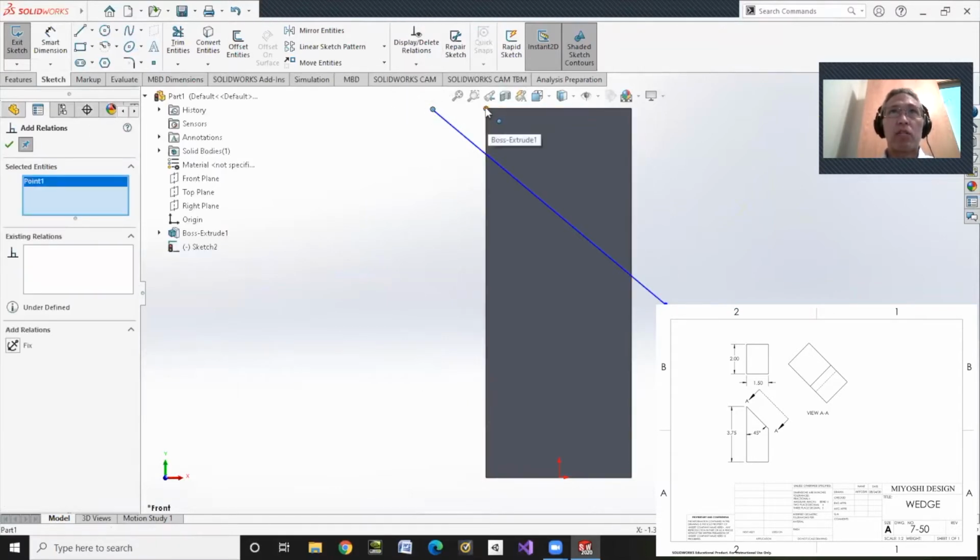Endpoint there, and even though there's really no point there, the intersections of lines and the intersections of faces is a point. So I'm going to make a point there. Grab that point, and I'll make them coincident. I will also make this line and this face coincident.